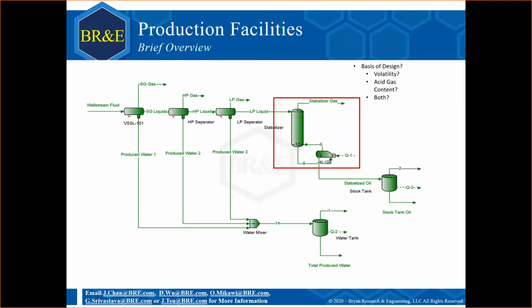This is where the entrainment becomes very important for the accuracy of your results. Because as we all know, the heavy liquid portion has its own saturation point with acid gases and its own thermodynamic properties with acid gases. So the ability to model a 3-phase tower where you can see your water phase, your hydrocarbon phase, and your gas phase all interacting with each other and all performing mass transfer on each other allows you to generate a more accurate system in order to figure out what reboiler duties you need to run the system effectively and to hit your product specs.